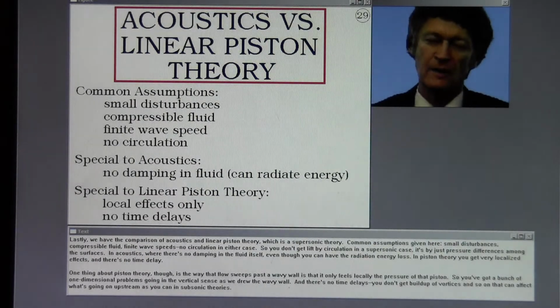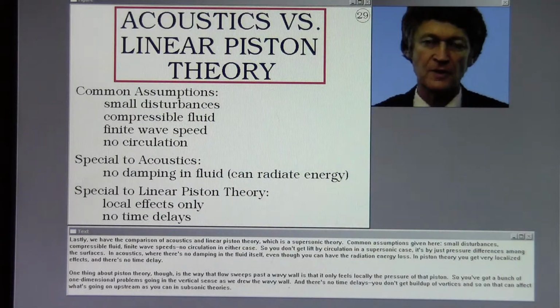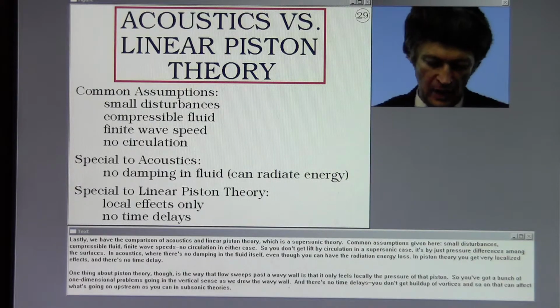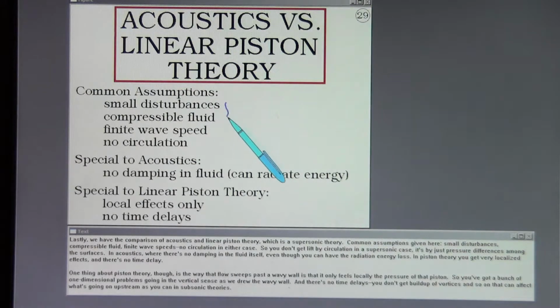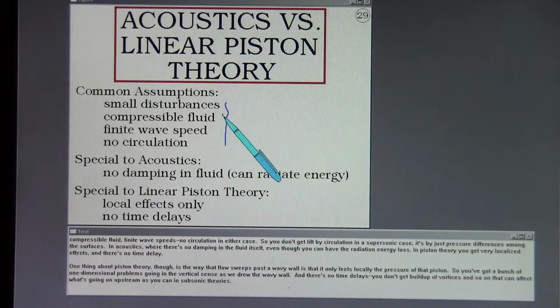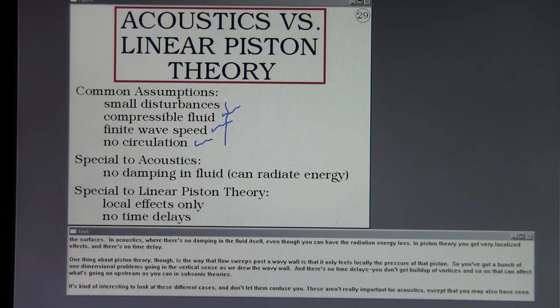Lastly, we have the comparison of acoustics and linear piston theory, which is a supersonic theory. Common assumptions given here: small disturbances, compressible fluid, finite wave speeds, no circulation in either case. So you don't get lift by circulation in the supersonic case. It's by just pressure differences among the surfaces. In acoustics, there's no damping in the fluid itself, even though you can have the radiation energy loss.